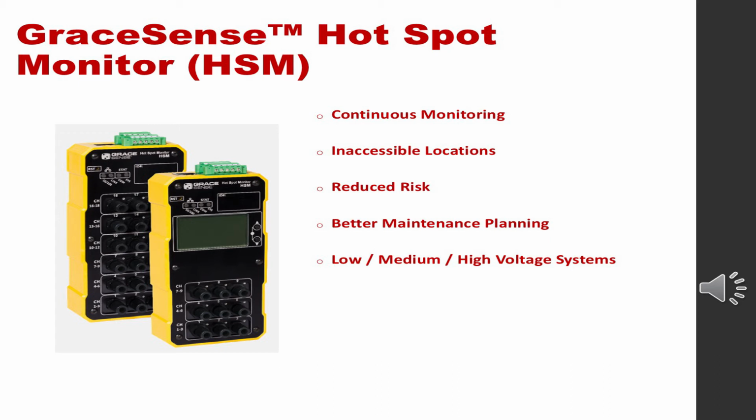Some of the key things I would like to highlight with this device are that it continuously monitors the temperature, unlike thermography programs where you measure the data more so on an annual or semi-annual basis. With thermography programs, the data is more so intermittent readings, right? With this device, you can continuously monitor and also log the temperature data. The next point here is to monitor the connections that are not visible to the line of sight. With thermography cameras or the windows, you can only see what you can see with your plain line of sight.